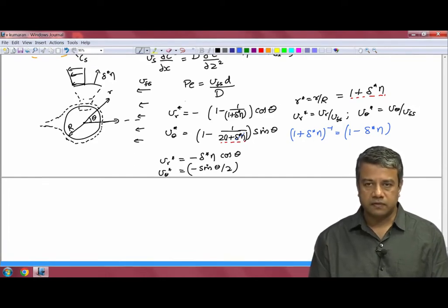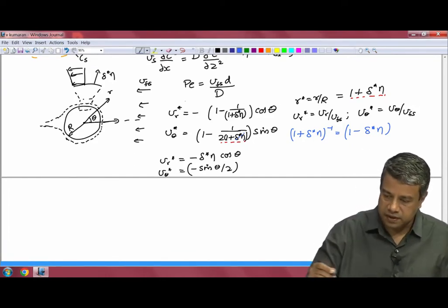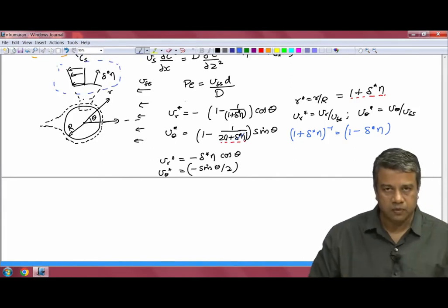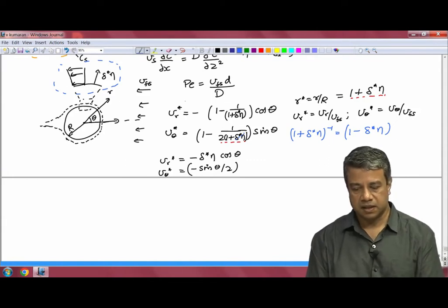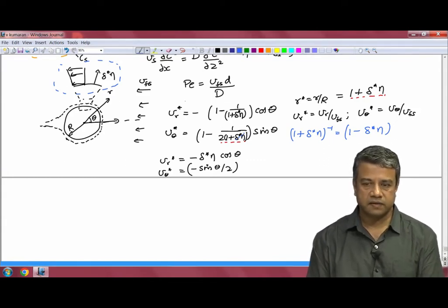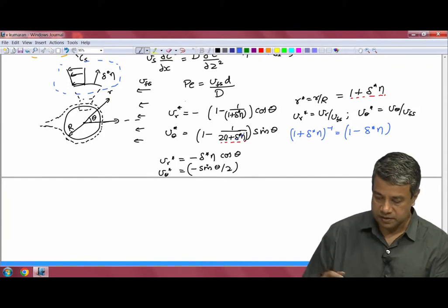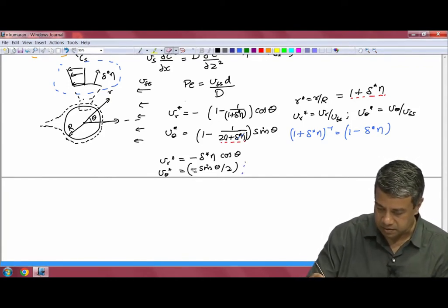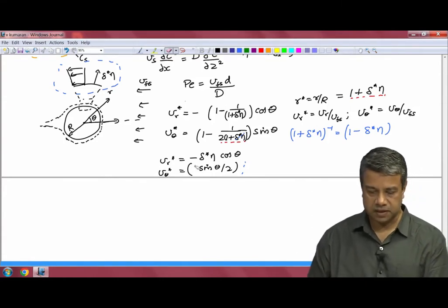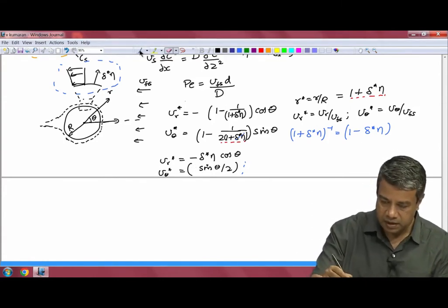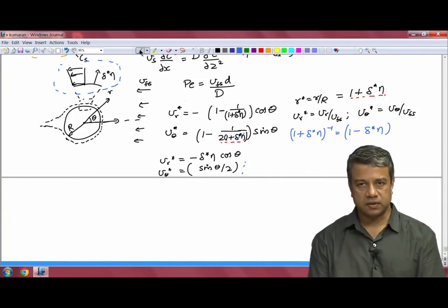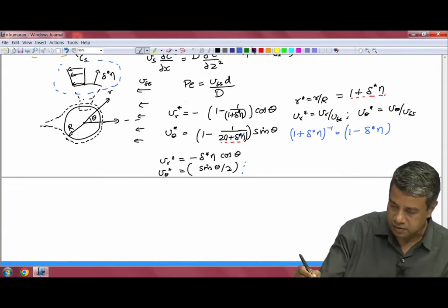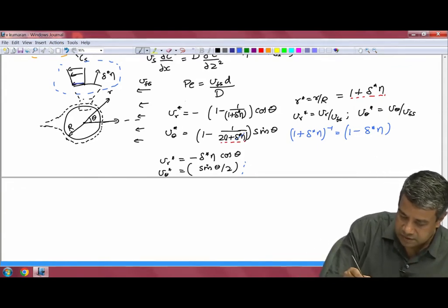Note an important difference, as I have shown in this figure on the left here, between the case of a mobile interface and a rigid interface. In a mobile interface, the tangential velocity is non-zero at the surface, as indicated by this non-zero value of V theta. There should be no negative sign, there is just a positive sign, kindly correct that. The tangential velocity is non-zero, in the plus theta direction around the sphere, as shown by the non-zero value of the velocity at the surface over here.